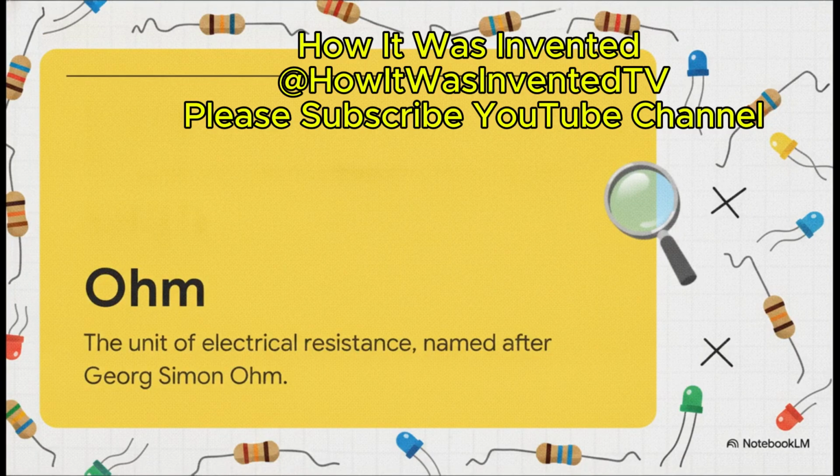When you look at real macro photos of modern resistors, you'll see they are often these tiny little cylinders with brightly colored stripes painted around them. Engineers actually read those stripes exactly like a barcode, so they can instantly know the resistor's value without even having to test it. And these things are absolutely crucial. I mean, almost every circuit with an LED has a resistor sitting right next to it just to limit the current. Without it, way too much current would rush in and burn that delicate LED out in a fraction of a second.